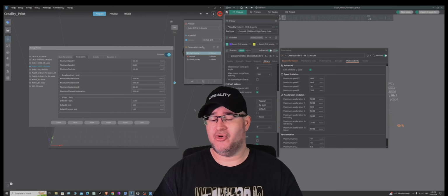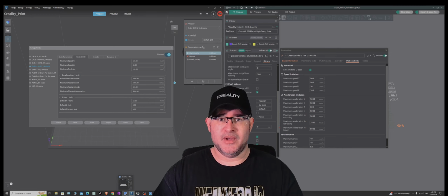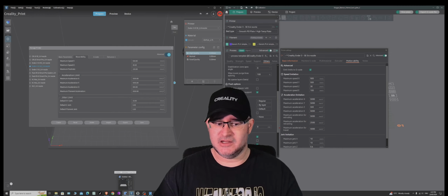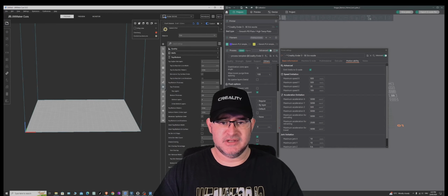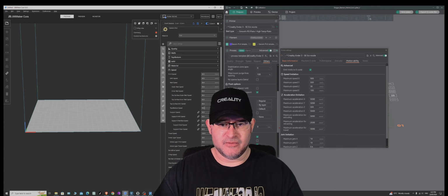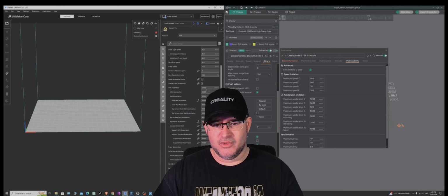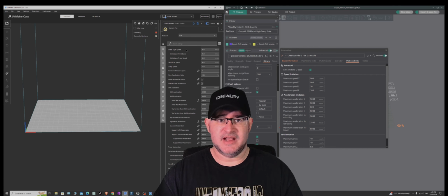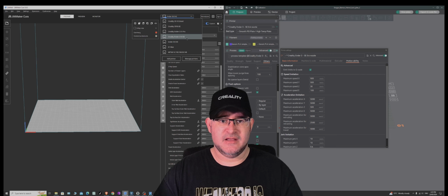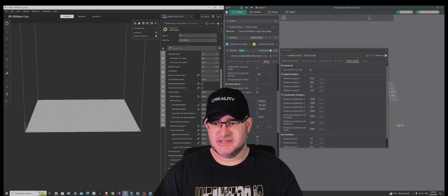Now you will find Cura is a little bit different, in that when you go into Cura, you do have to enter these manually. So when you go into Cura, for instance, we'll go into our speed settings, and when we scroll down here, we've got all these settings set at 5,000, and that's for the KE. Now, if we go to the SE and switch that around, you can see that they're all 2,500 and so on, whereas some of these ones are at 5,000. So there's a bit of a variance there, which you need to play around with.